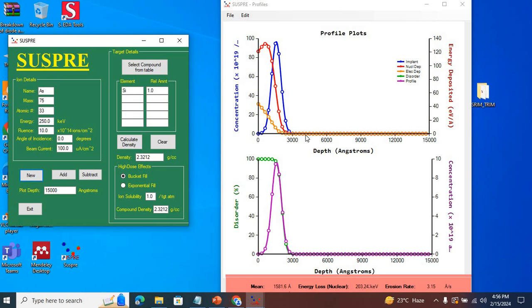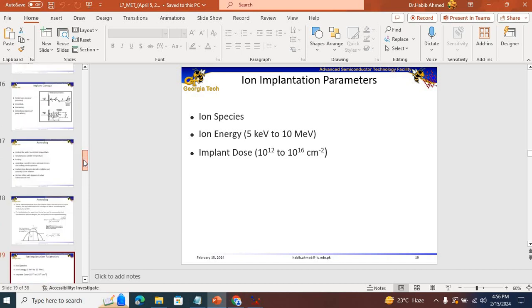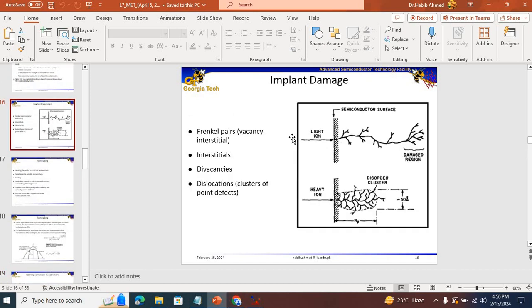Also, in case of boron doping of silicon, we observed a range of 700 plus nanometers. In case of arsenic doping of silicon, now the range has reduced to 158 nanometers. It also clarifies our point that lighter atoms travel deeper into the host material, while heavier ions travel shallower into the host material, or into the substrate.